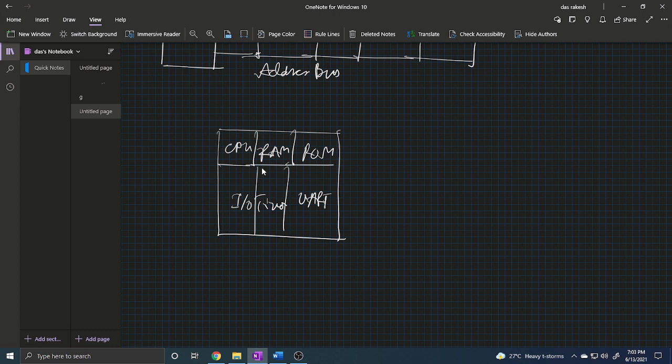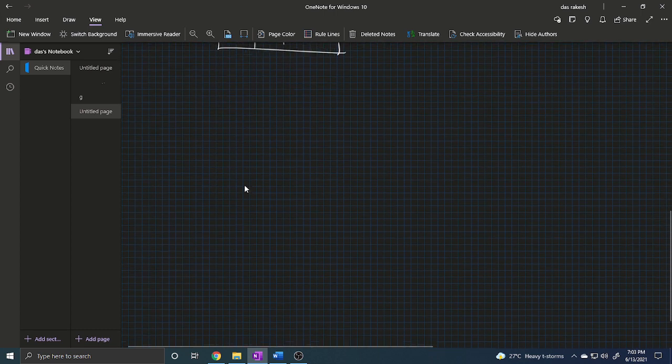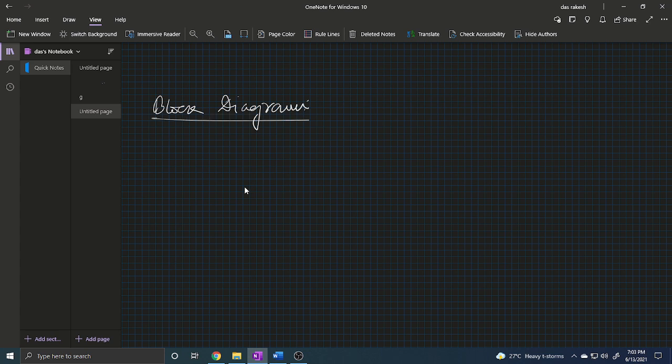Okay, so first of all we discuss the overview of the 8051 family. Before discussing the 8051, there is a basic concept of the block diagram, so first we discuss a brief block diagram. Here we discuss the block diagram of an 8051 CPU. Here is the main CPU. In this CPU, the general purpose registers, arithmetic logic unit, and the control and timing unit are present. And with this CPU, one crystal oscillator is connected.